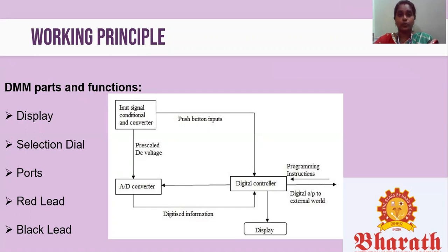The third is ports. Two ports are available on the front of every multimeter, except in some where 4 ports are available for measuring current in mA or A. COM stands for common and is almost always connected to ground or considered the negative connection of a circuit.